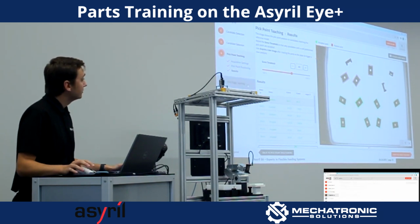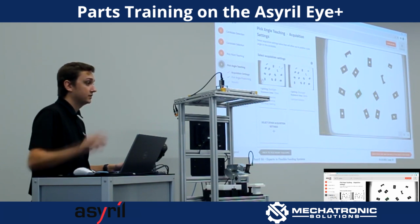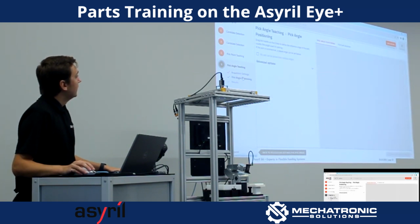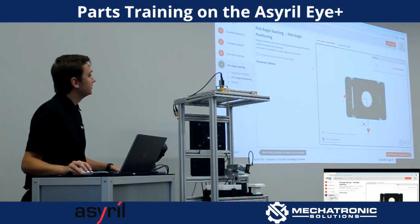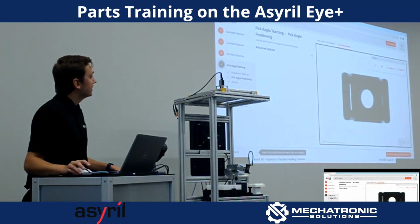So the next step is pick angle. So we want to define the angle at which we pick. When I+ sends coordinates to the robot, it's going to give a rotation as well, and that's where the part is angled on the platform. And so we want to be able to define the angle that we want to send. And so this is where you would set your robot's X, Y axis and rotation, and how you want to essentially center that.